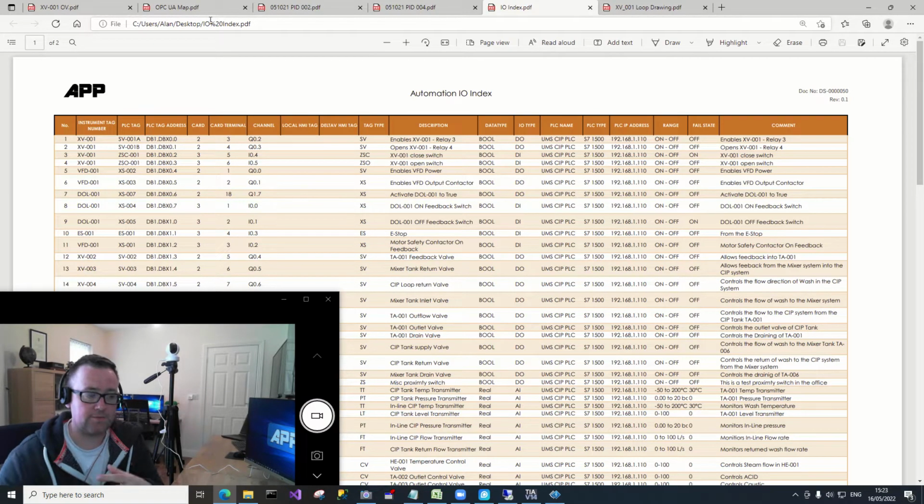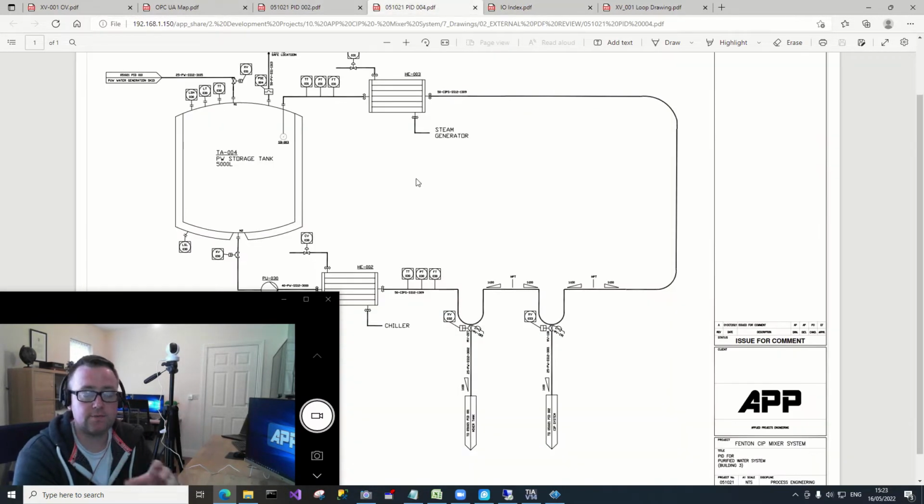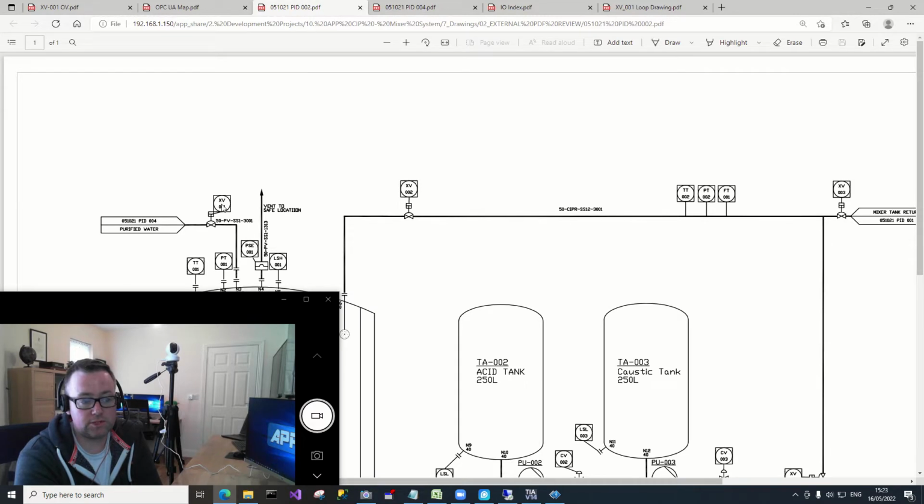Normally, if you're in a situation like this, say we have this purified water system, and we'll pretend this is a vendor package controlled by a non-standard PLC, maybe a Siemens PLC, and our DeltaV system has to reach out to it. We might want to take control of some of the instruments, but certainly we want to do readings from the separate vendor package. A typical scenario here: I have this valve and it's going to take in actual water from our purified water system to fill a tank.